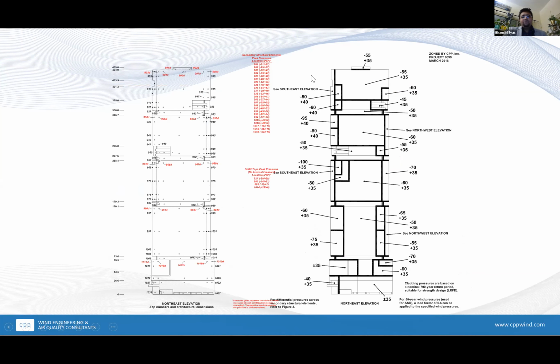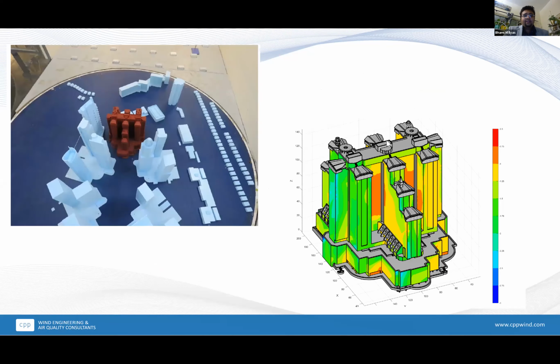One of the ways this looks is in terms of facade pressures, which is what you're looking at here in PSF. You can see here we can identify, in a particular building on an elevation, how these loads vary. In some places it's 100, some places it's 50, and so on. So the curtain wall consultant looking at this is going to process this further once we hand it over, to look at what kind of cladding needs to go in. In terms of the results, we have different approaches, and every client and every design team we work with has different recommendations and approaches, and based on that we tune them. This is another beautiful project that we worked on recently in the region.